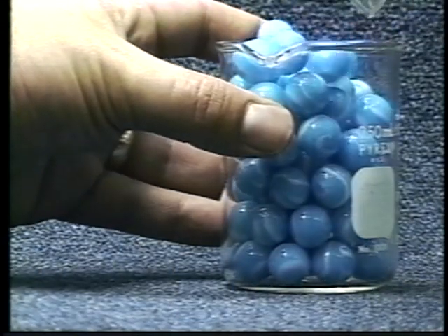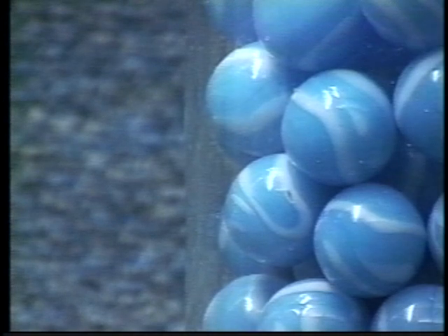Consider this simple model of a cubic aggregate surrounded by spherical cement particles. To see how the cement packs differently close to the aggregate, the model is first flipped over. Then we fly through the cement towards the aggregate. This final slice is taken right in front of the aggregate. The middle region shows extra porosity because the cement particles cannot pack themselves efficiently near the surface of the aggregate. It is sort of like pouring marbles into a jar. Toward the edge of the jar, the marbles pack themselves much less efficiently with more porosity. This is often called the wall effect.